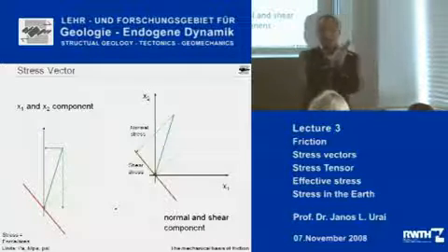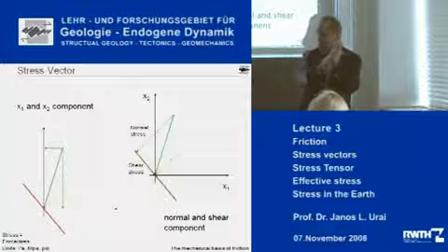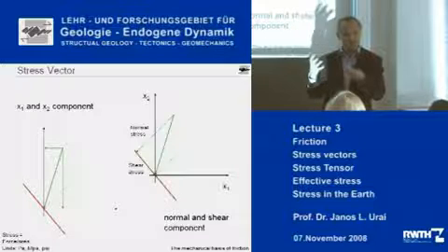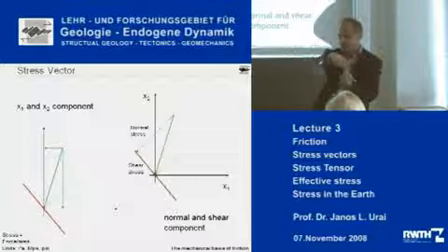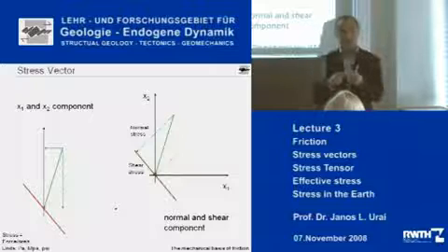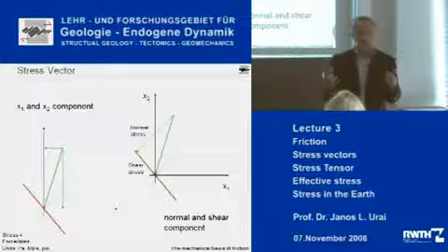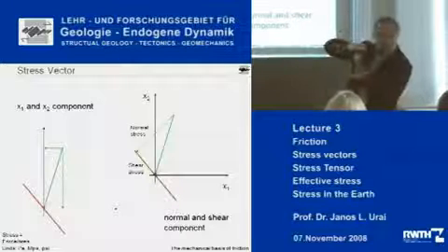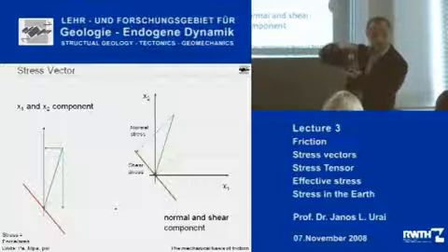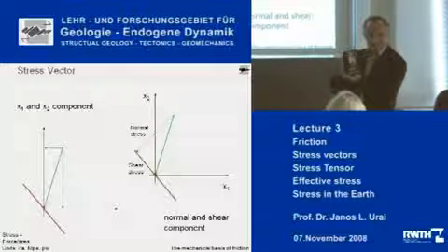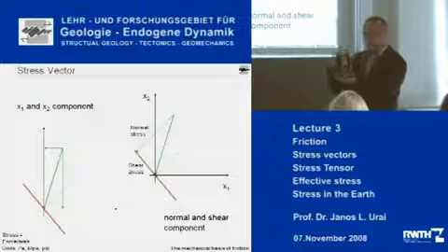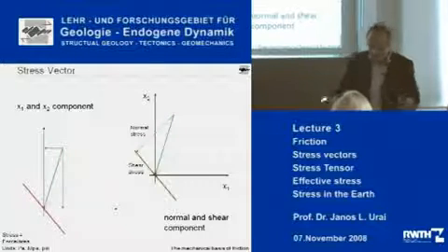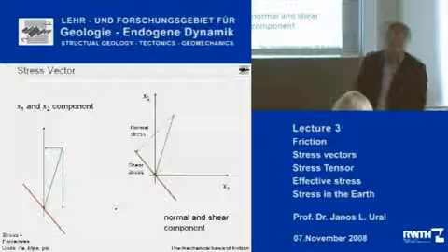If I have a plane, maybe a fault plane in the Earth, for example, or just a sheet of paper, then it is actually not so difficult to conceptualize, to understand the notion of this stress vector. It is simply the force divided by the area. What is more difficult is trying to figure out, in this direction and in this direction, there are infinitely many planes in this piece of solid, and on each of these planes you could try to figure out what the stress vector is. So my next slides are going to illustrate this question in a little more detail.